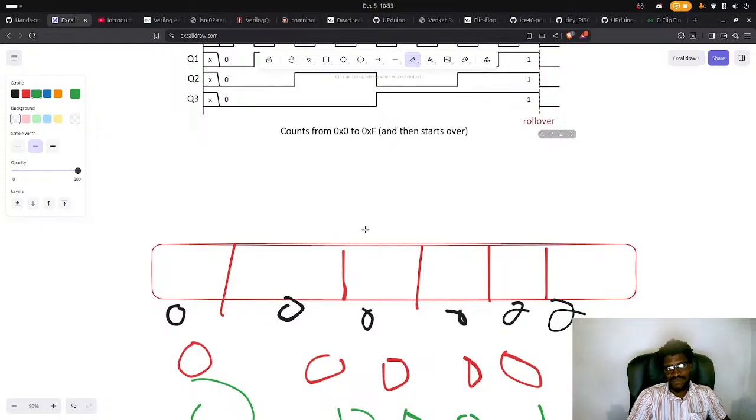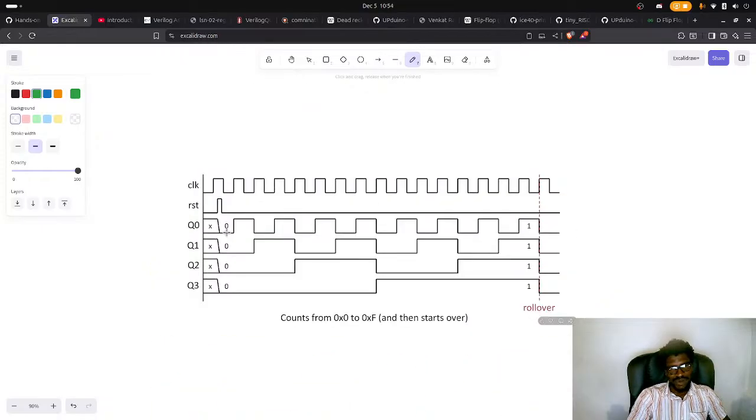So for every time this clock flips here, we want to add 1 into this 4-bit thing. It starts out at 0, 0, 0, and we want to reset it all when it gets to 1, 1, 1. Okay, so every time, the first thing we do is we apply a reset. All the 4-bit value starts in unknowns, which is x's.